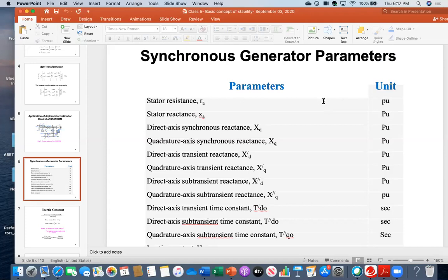For example, in a big network, you will be dealing with several thousand volts or several hundred amperes. Therefore, those will be big numbers. You want to calculate power, then again it is a very big number. Even though you convert into megawatt or kilowatt, still those will be big numbers. In order to avoid those big numbers in power systems, there is a system which is called per unit, PU. So what is the definition? Actual value divided by base value.